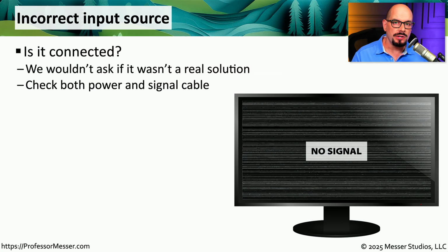If you've ever turned on your computer, but your screen is black or gives a message that says no signal, then you'll need to do a bit of troubleshooting to determine why that's occurring. One of the first things you'll probably want to try is also one of the easiest. You'll want to find out if the monitor really is connected properly. You should check to make sure that the video cable between the computer and the monitor is connected and that the connections are pushed in completely.